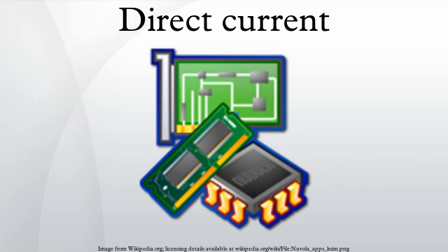Various definitions. The term DC is used to refer to power systems that use only one polarity of voltage or current, and to refer to the constant, zero frequency, or slowly varying local mean value of a voltage or current. For example, the voltage across a DC voltage source is constant as is the current through a DC current source. The DC solution of an electric circuit is the solution where all voltages and currents are constant. It can be shown that any stationary voltage or current waveform can be decomposed into a sum of a DC component and a zero mean time-varying component.